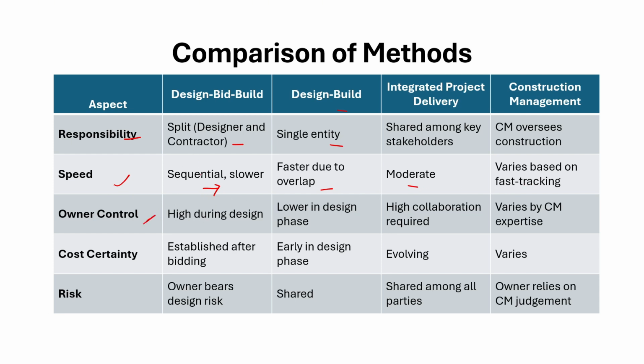For owner control, in design-bid-build it is higher during design. The owner control is lower in the design phase in design-build, while in IPD high collaboration is required because all parties are involved during the process. And in CM, it varies by CM expertise.